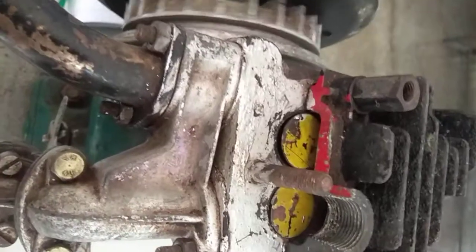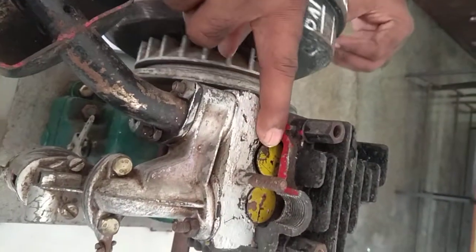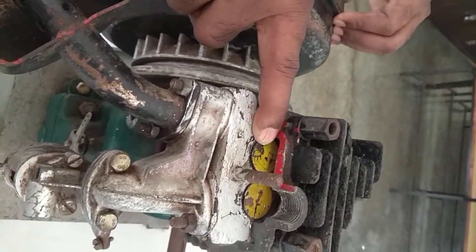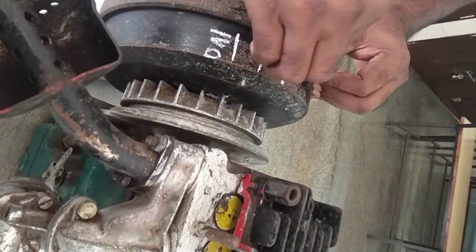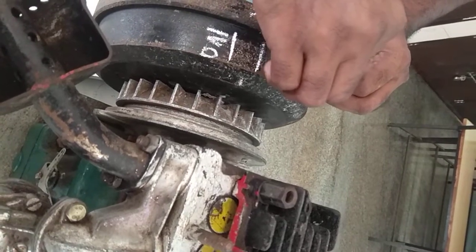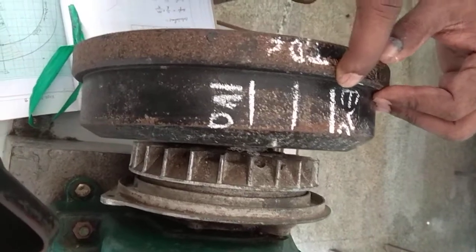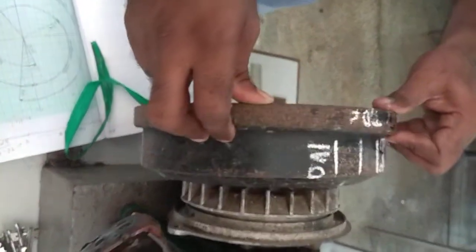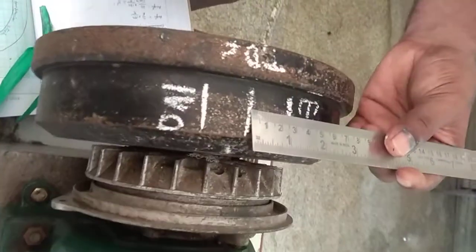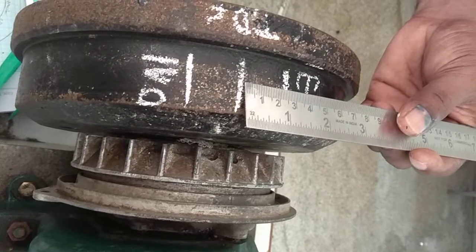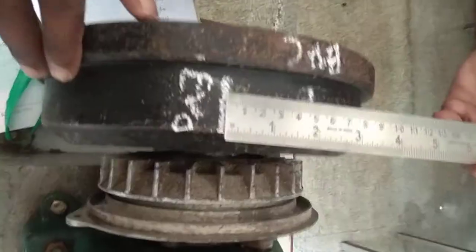Next we will note down the closing of the exhaust valve. Keep rotating the wheel. Now you watch, here the exhaust valve has closed. With respect to the reference line, mark the exhaust valve closing value. This is after TDC, because after TDC the exhaust valve closed. Measure the value with respect to TDC. It is around 24. We have marked everything.